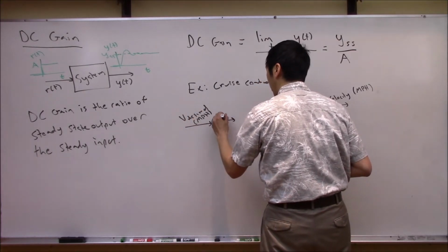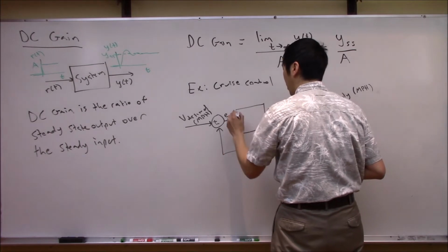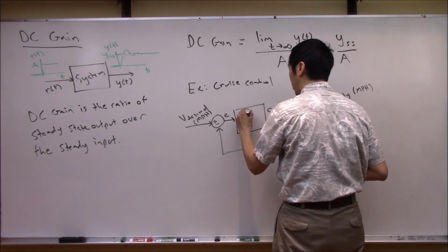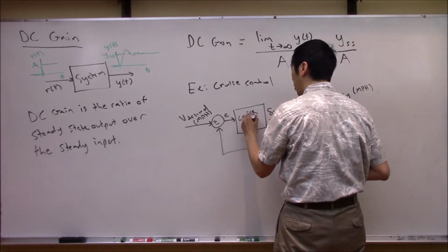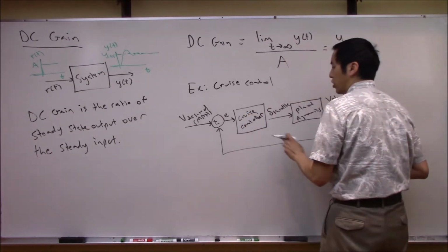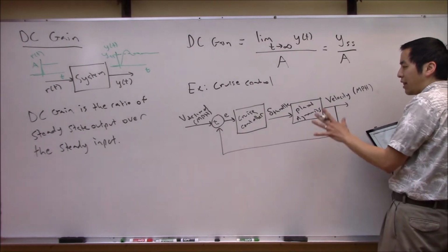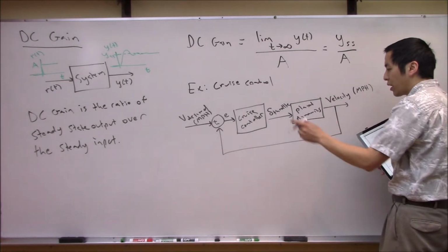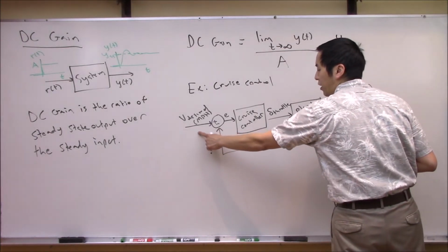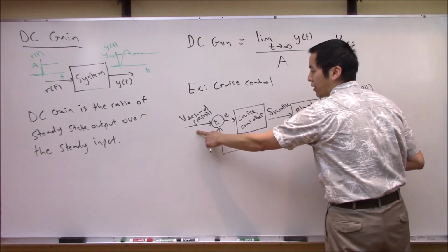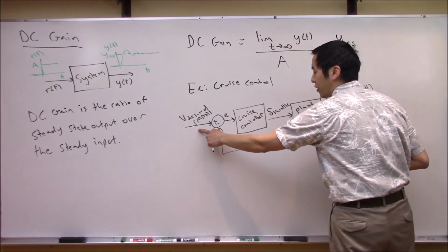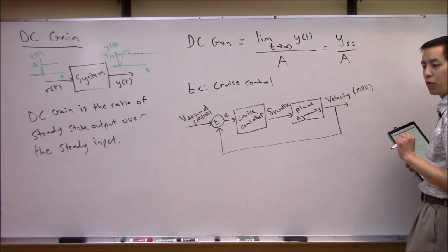And that generates some kind of error signal, and then you have some kind of a controller, which is in this case your cruise controller. And this will be in charge of actuating the gas here. And hopefully what you would like at the end of the day here, right, is that when the operator here, when you as the driver specify some kind of desired velocity, eventually the car will reach that velocity.